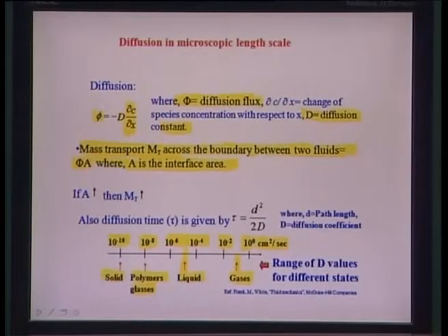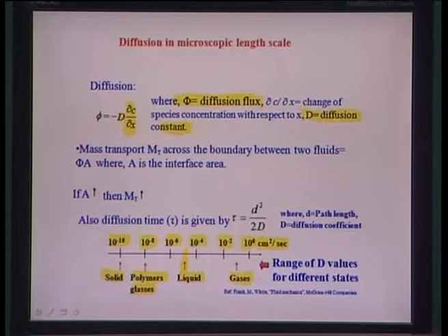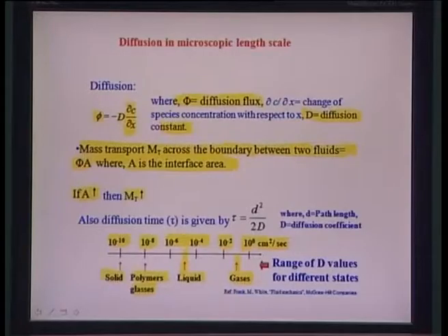So therefore interfacial area in such cases becomes highly prominent, especially when mixing is concerned. If you have somehow a mechanism wherein you can accommodate two flows over a larger amount of area, automatically their mass transport would be more. Sometimes it becomes architecturally promising to design micromixers where this area of interface between the two flows is increased, resulting in more mass transport. Okay. So if area is more, then the mass transport Mt is more.